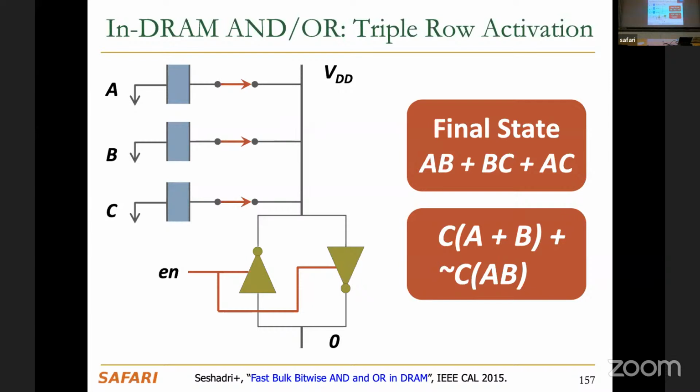Well, that's true, but it's also true that it would be relatively easy to prevent. For example, with isolation rows, that is one of the ways of alleviating RowHammer that people have proposed. Because these rows are in a very specific part of the subarray, we could have some isolation rows. Anyway, if you want a better discussion about the possible effects of RowHammer, I can recommend a follow-up of this Ambit paper that is SimDRAM. There is also a link in a later lecture, and there we have a short section where we discuss RowHammer.